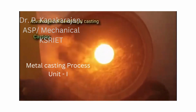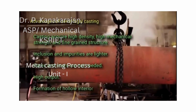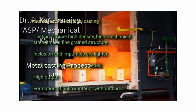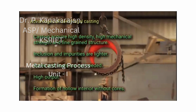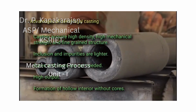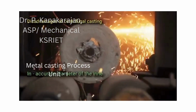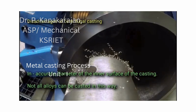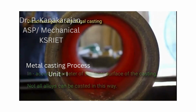Advantages of centrifugal casting. Castings acquire high density, high mechanical strength and fine-grained structure. Inclusions and impurities are lighter. Gates and risers are not needed. High output. Formation of hollow interiors without cores. Disadvantages of centrifugal casting. Inaccurate diameter of the inner surface of the casting. Not all alloys can be cast in this way.